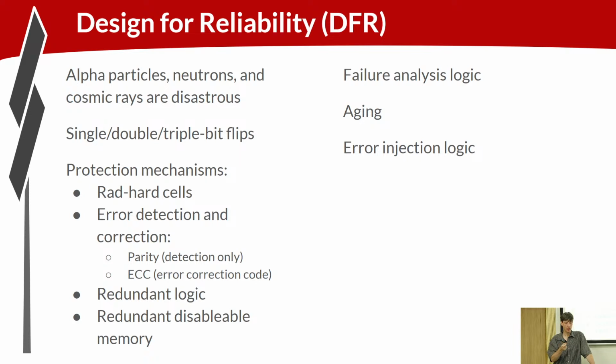Memories in particular account for a fairly large surface area on our die. The circuits are very compact and very susceptible to these particle strikes. If one of the bits flips in memory, it depends on the software, but that's a potentially visible impact to the program.